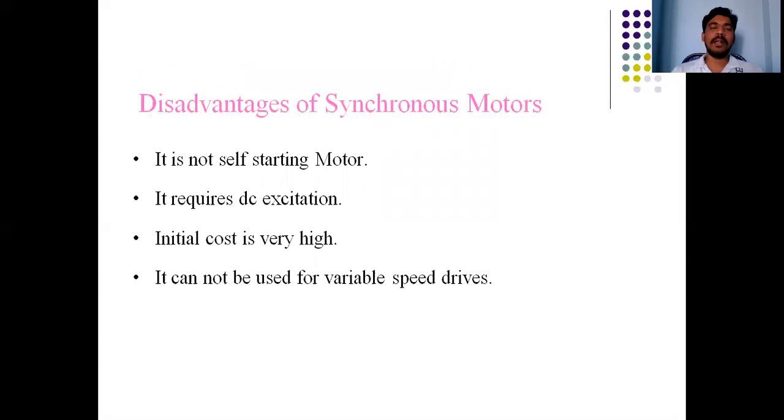Coming to the disadvantages, it is not a self-starting motor. We need an additional device, either a damper winding, a pony motor, or an induction motor. Different methods are needed to start the motor. So it is not a self-starting motor.